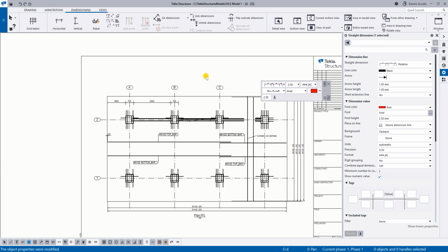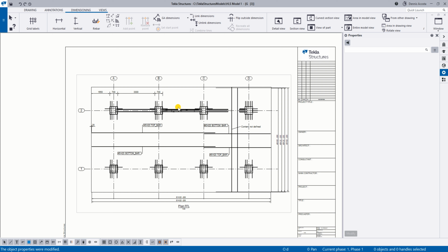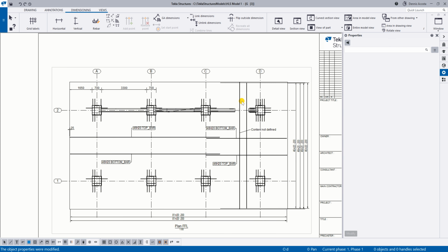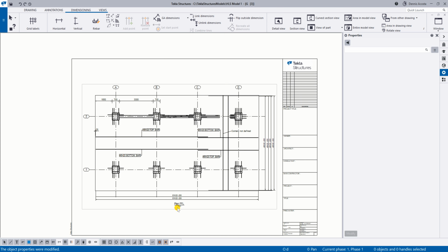Yeah? So you want to try this one first, and then after this, I'm going to show you how to create the cast unit drawing. Cast unit drawing. So meaning an individual part, if you want to extract an individual part, then we can create an automatic drawing for that. Okay? So at the moment, use this one. Do this one.